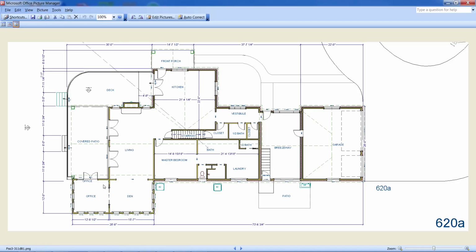The next thing I wanted to mention, right now, at least as near as I can tell, it's going to make the most sense to frame the walls of these two new rooms at standard 97 1/8 high and finish out about 8 foot finish inside. And you're currently finishing out at about 8'4". So there would be a difference there.